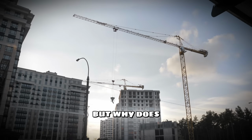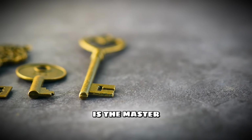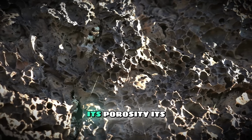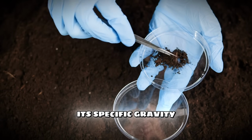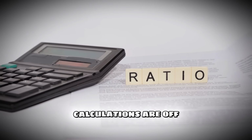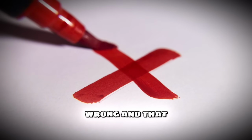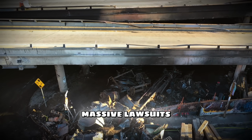Simple, right? But why does this simple number matter so much in the real world of construction? Because specific gravity is the master key that unlocks every other critical soil calculation. You absolutely cannot calculate a soil's void ratio, its porosity, its degree of saturation, or its critical density without first knowing its specific gravity. If your specific gravity numbers are off, your void ratio calculations are off. If your void ratio is wrong, your estimates for how much that soil will compress under the weight of a skyscraper will be completely wrong. And that is exactly how you end up with cracked foundations, sinking highways, and massive lawsuits.